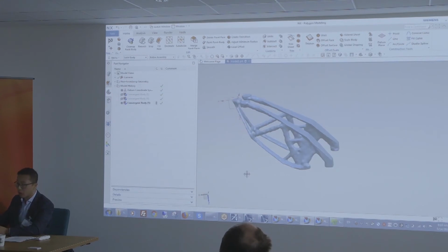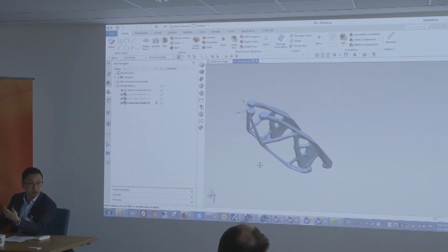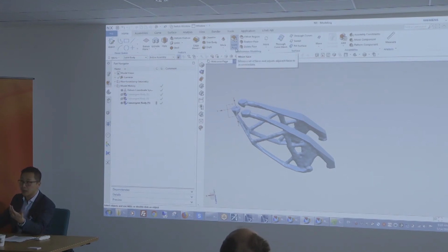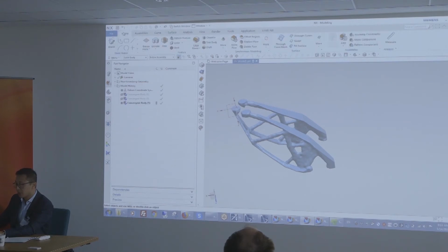Yeah. You can directly import it, and see we have kind of a smoothed geometry. Now there's a lot that can be done, so I won't go into the nitty-gritty details, but we have all the tools available now that you're used to, like all the extrude, the synchronous modeling tools to add geometry, to create holes. But we can also use our NX Realize Shape tool to create those A-class surface or B-rep surface around it that are parameterizable, right? Because sometimes you want to maybe do optimization or parameterize your surface modeling around this. So you can still do it.